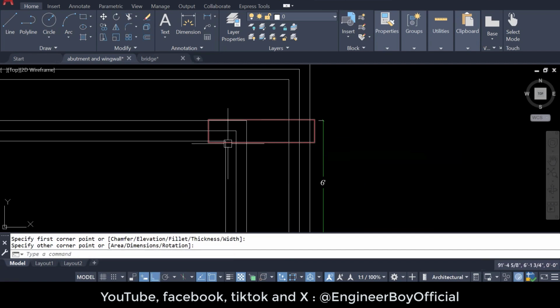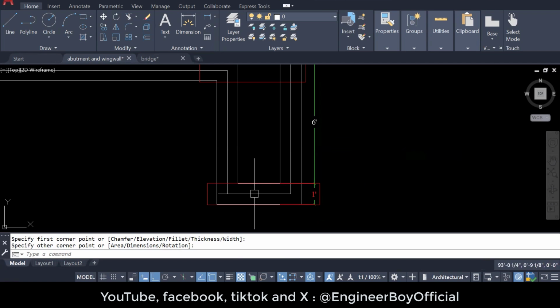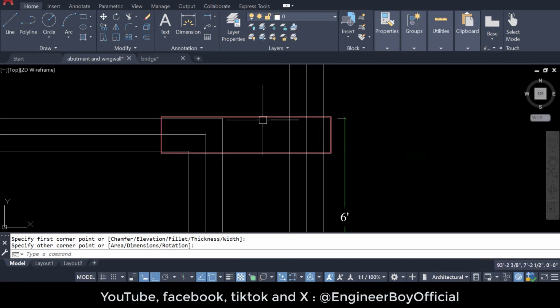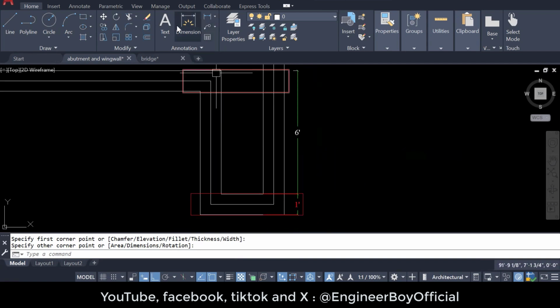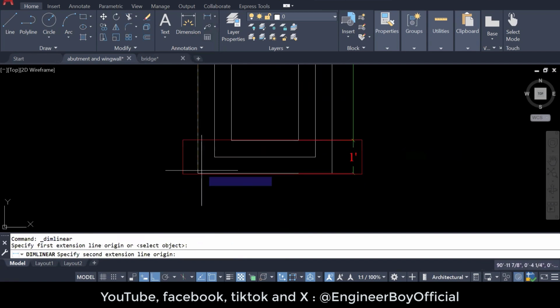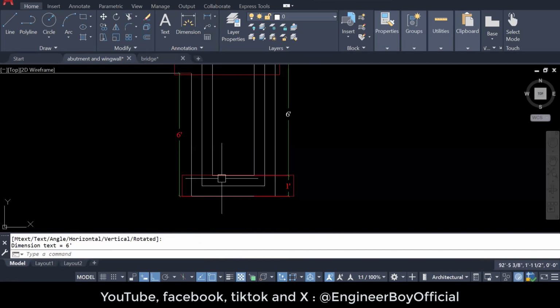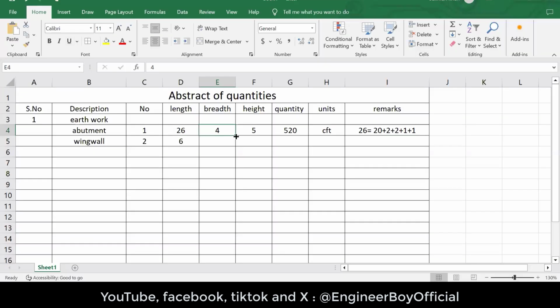These two steps are taken from the wing wall. So if we add these two, it means we can subtract those two. Very simple. So it is the same thing, from this point till this point, as 6 feet. We are not counting this one. So it means 6. Now, of course, the width of foundation is the same, which is 4.